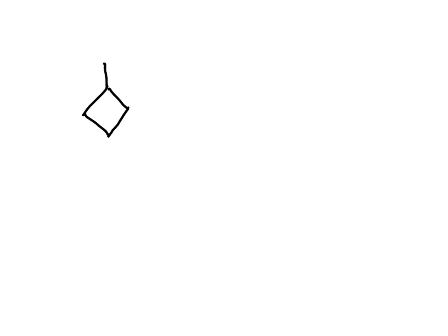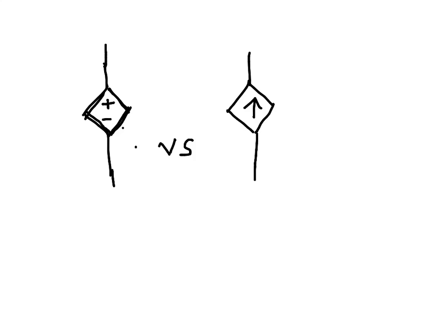For the voltage source the symbol is plus minus, and for the current source it is an arrow, but because they are dependent sources the symbol is a rectangle, just a light one. So basically this is a voltage source and then this is a current source, but it can depend on the voltage across a certain terminal or the current through a certain element.